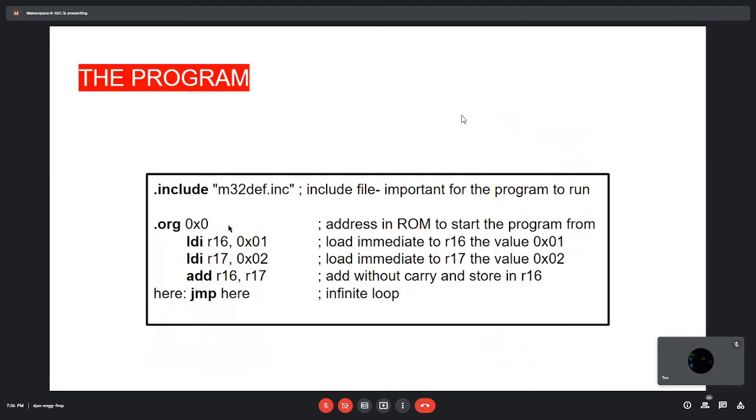So this program is written in assembly language. I won't go in depth into assembly language. It is just .include m32def.inc. This is an include file. It's important for the program to run. There are some rules and regulations here which are important for that specific microcontroller. It says M32 because it is an ATmega32, the big microcontroller here. That is why we have this file.